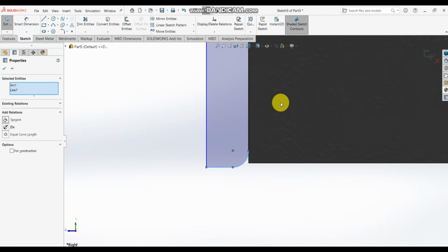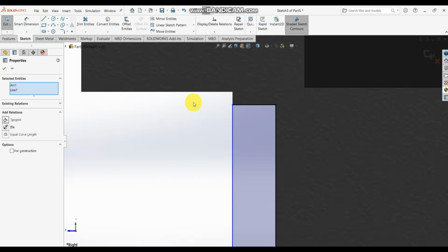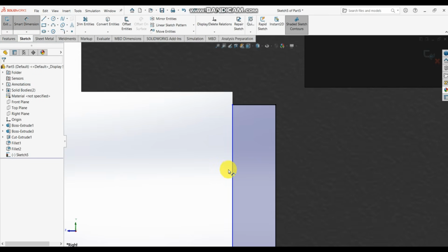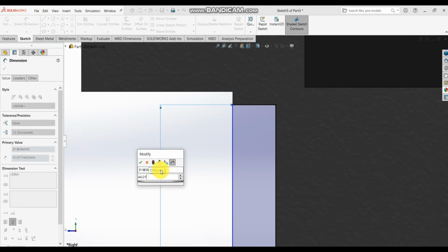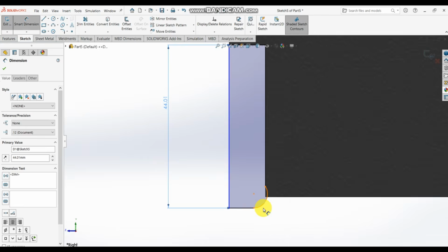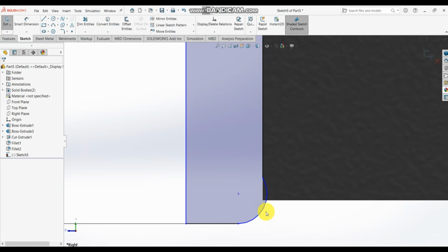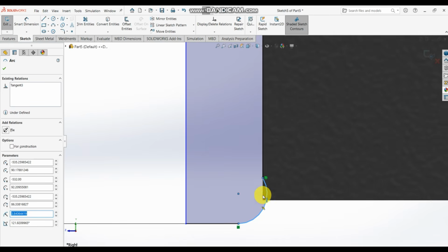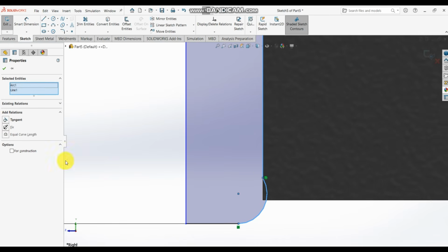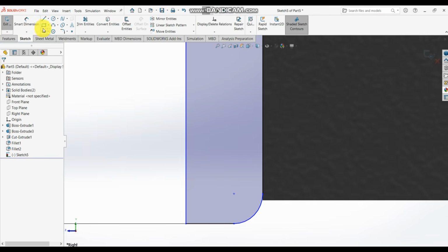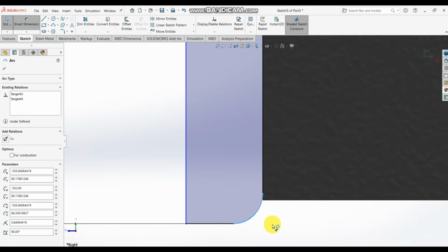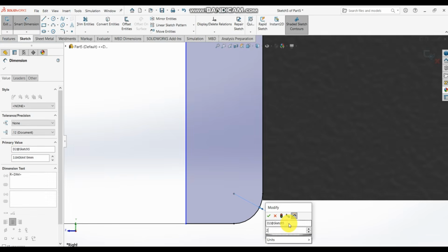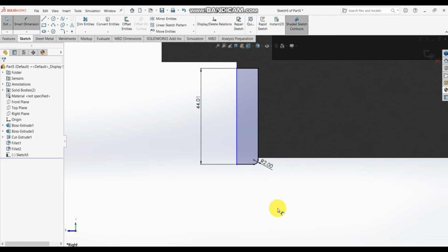So I have to see how I can dimension it. Watch. Please watch. So I come to dimension. I click here. I dimension it 44.01. Enter. And okay, watch please. And I also click on this. I hold my control and I click on this line. Make it tangent again. You see? I just click and hold the control. And I dimension. So I click here. I'll put a radius of 2. Enter. So you see the shape now. So I'm good to go.